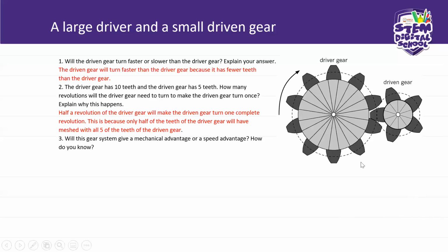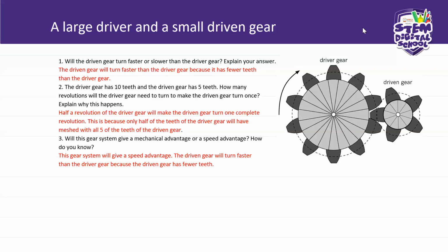So this system gives us speed advantage, not mechanical advantage. Will this gear system give a mechanical advantage or a speed advantage? I have just given you the answer. It will give us speed advantage because the driven gear will turn faster than the driver gear.